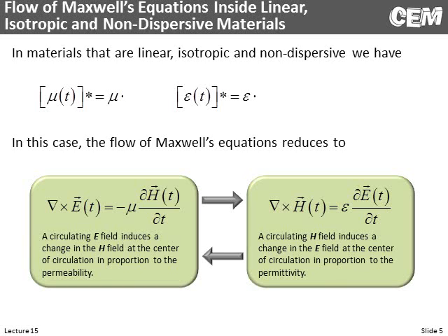That set of values starts to move across the grid. We continue to inject this Gaussian type source, and we're going back and forth at each point of the grid, and we can watch that wave propagate across the grid. And if there are any devices, we can see the field wrap around that and do other crazy things. But it all comes from back and forth with Maxwell's curl equations. So that's the gut feel of how finite difference time domain is working.